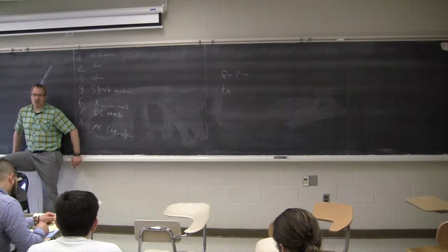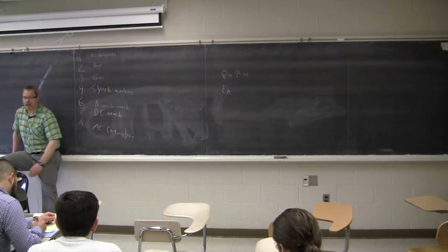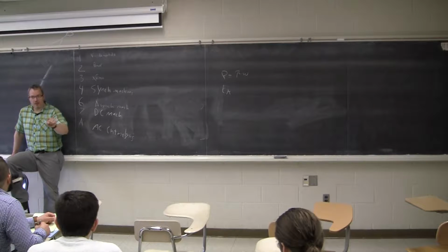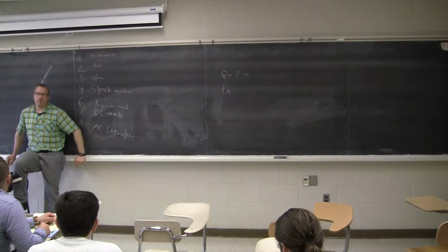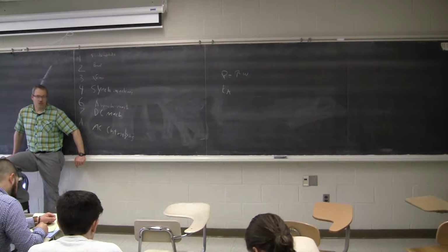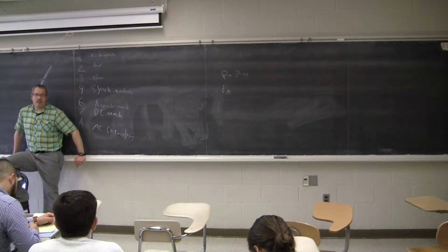R and X do not change just because time has evolved. In a phasor, you're walking through the sine wave, so if you look at time, the voltage that you see changes constantly. In an impedance, it's constant. It's just a resistor. It's just an inductor. It doesn't change. So understand the difference between a phasor diagram and an impedance diagram.